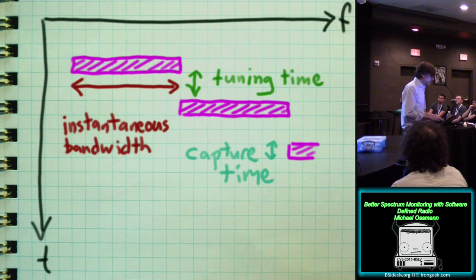And that's one thing that HackRF can give you that Realtek dongles can't: there's a clock input and output, so you can clock synchronize multiple devices. But that's only part of the calibration problem. Having synchronized clocks means that their frequency configurations will all agree with each other very, very precisely. But there's also the problem of their power measurements.